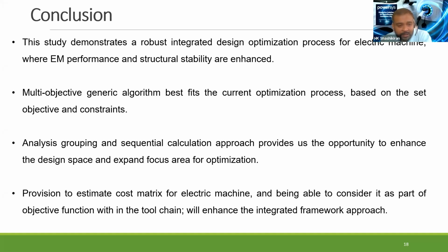So rotor inertia is critical for us because we are trying to get this integrated into the drivetrain, and the drivetrain already has some restrictions on how the behavior should be. We cannot completely redesign. So inertia is a critical factor because we need that initial torque and initial response, and also the user experience of the existing design was required. So we did not want to have major changes in our overall drivetrain or the gearing principle. Inertia was critical because we wanted the same user experience and the same drivetrain function.